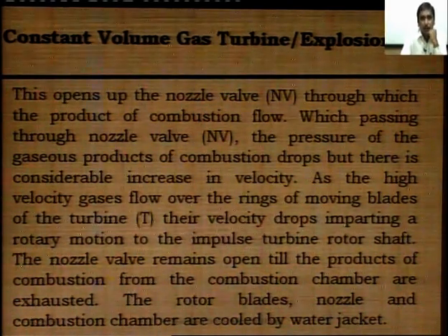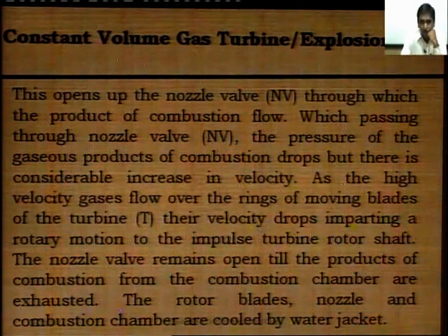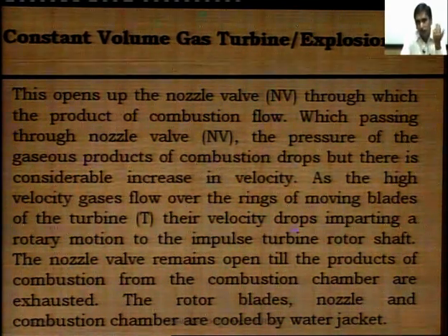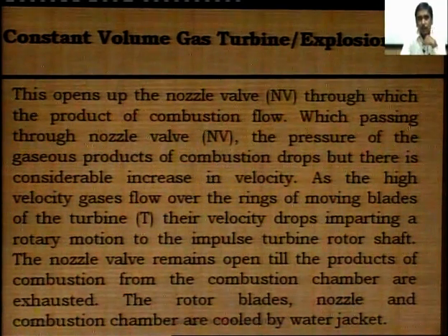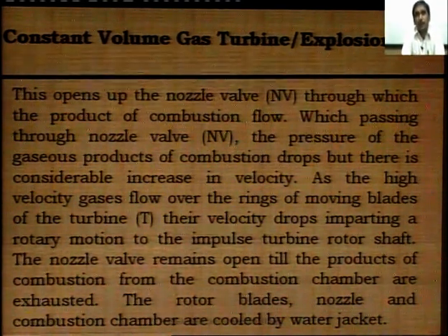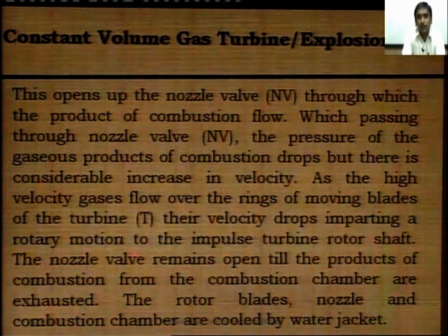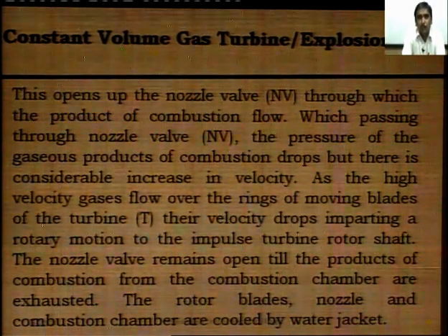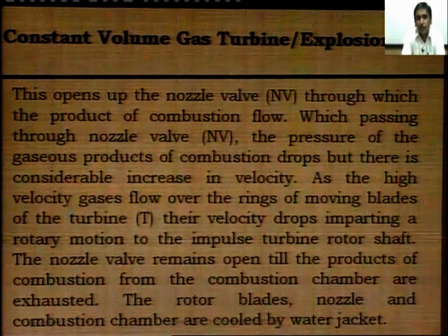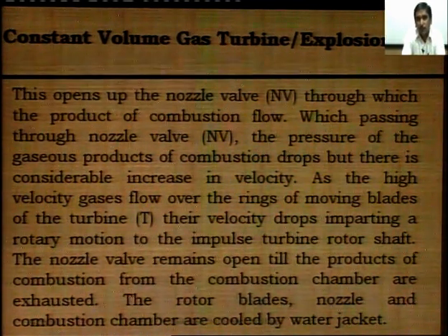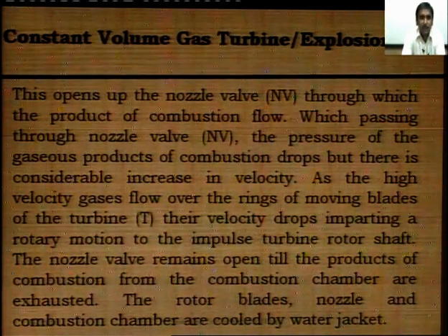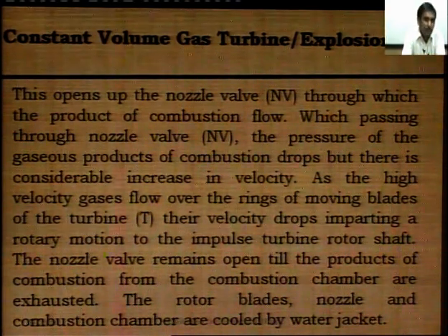This opens up the nozzle valve NV. When the explosion takes place, this opens up the nozzle valve NV through which the products of combustion flow. While passing through nozzle valve NV, the pressure of the gaseous product of combustion drops, but there is considerable increase in velocity.